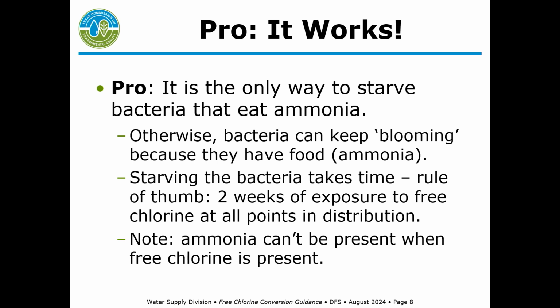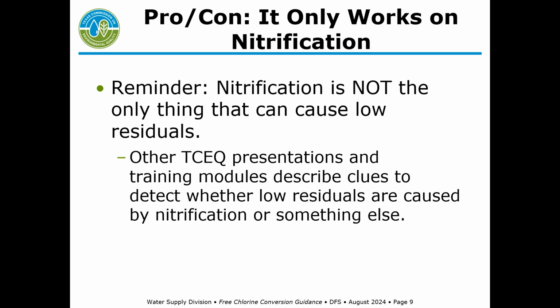When you do the conversion, as already stated, there can't be any ammonia present because you have free chlorine. They don't exist together. There are other things that can cause low residuals, and we're not going to really talk about them today, but there are other TCEQ presentations and training modules that help you figure out what's causing my low residual, particularly if it's not nitrification.